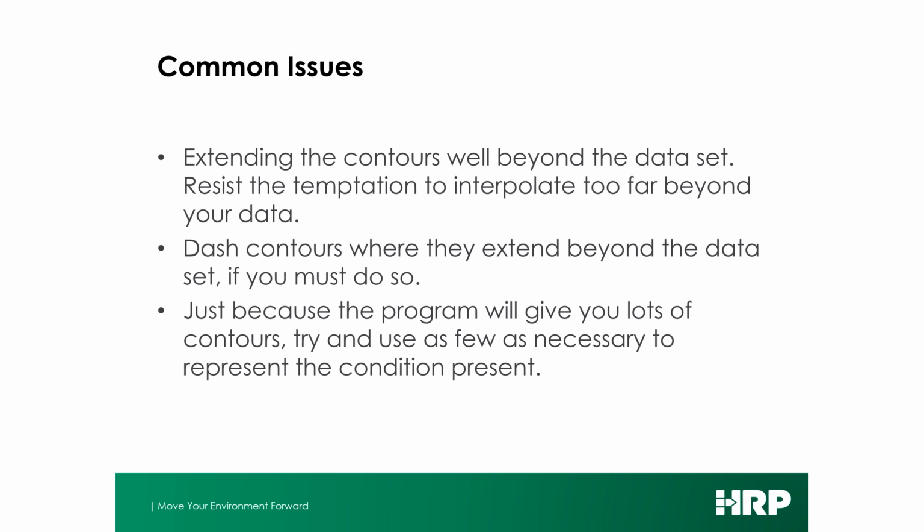Just because the program that you use gives you a lot of contours, you don't need to use them all. Sometimes they'll cover up all the other features, because it's about picking. A lot of programs have a default number of contours they'll try to put in regardless of the slope of the head differential in the water table.